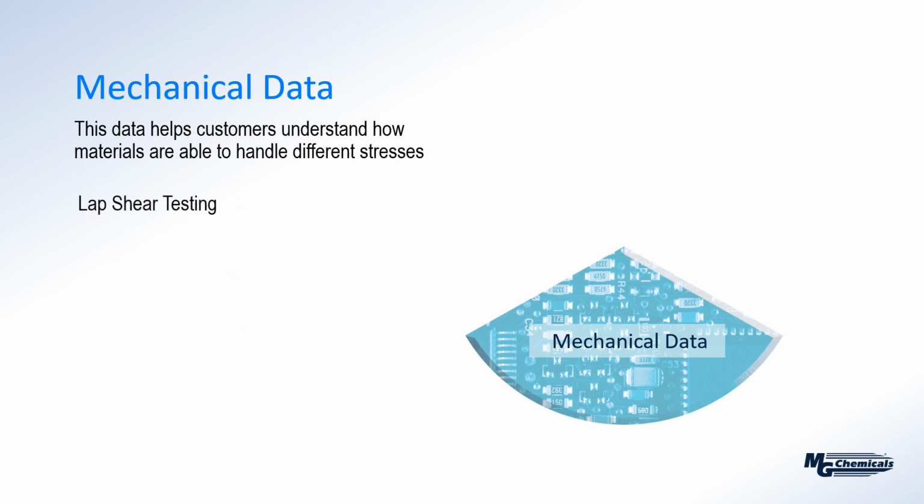And then finally, let's look at the lap shear testing. This is a test that looks at the relative adhesion of a material for different types of substrates. We make a lap shear: we overlap two substrates and they're held together in a thin section by the material itself. You place the ends of each side in vice grips, secure it very firmly, and it works very much like the tensile strength test.